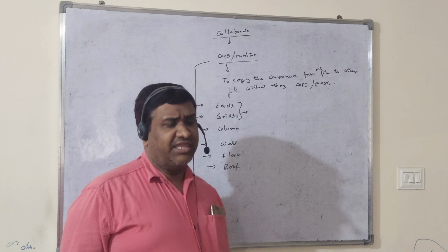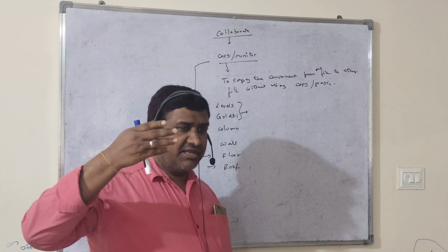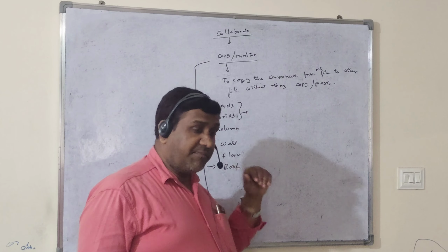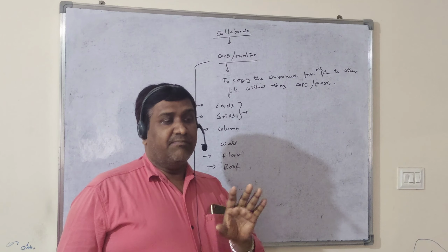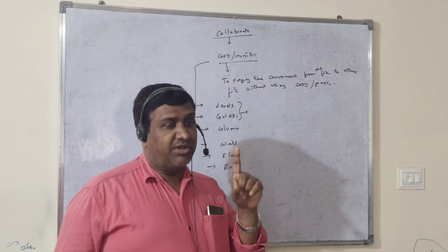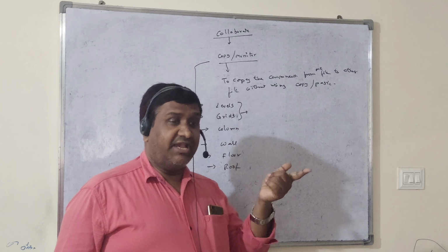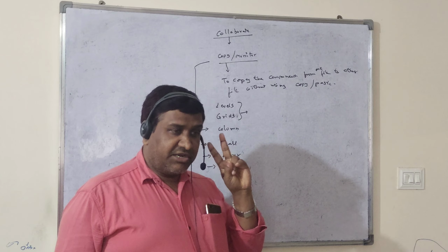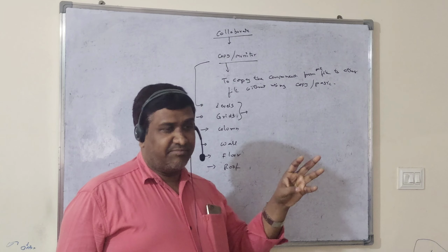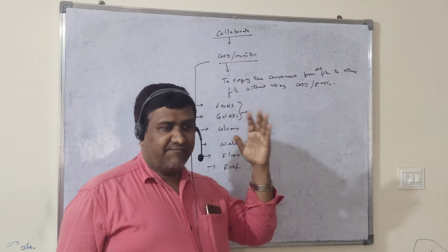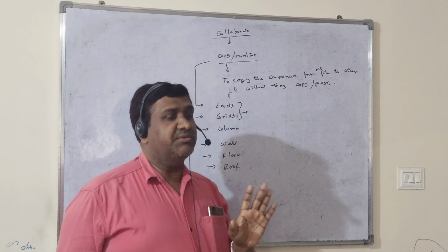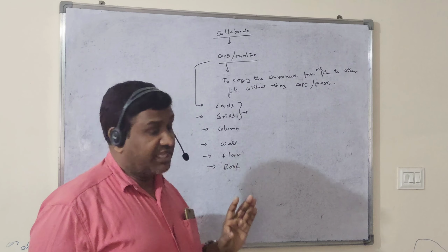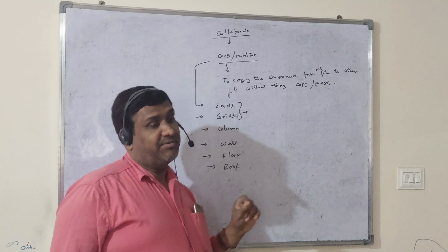Some people think that with an AutoCAD file we can also do Copy Monitor. It's not possible, because Copy Monitor is possible only when the other file is also a Revit model. With any other software, like 3ds Max, Pro E, Catia, Hypermesh, it's not possible, because the file format should be the same. Then only we can do Copy Monitor.